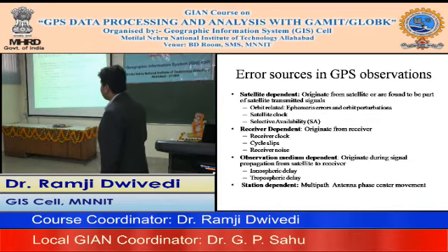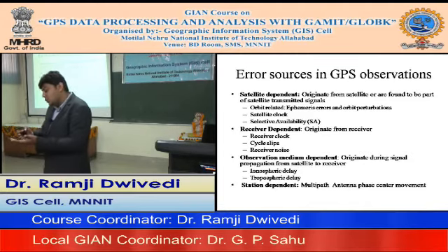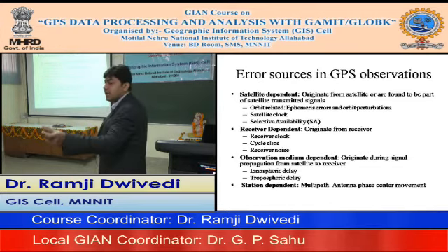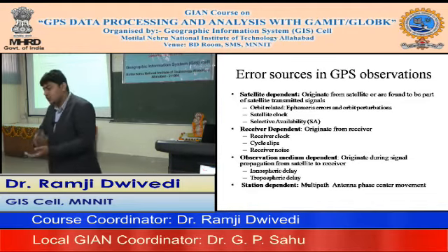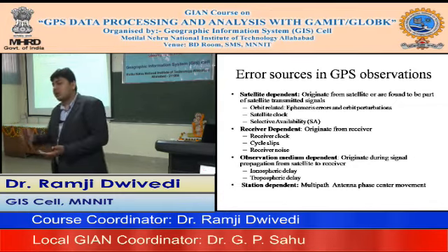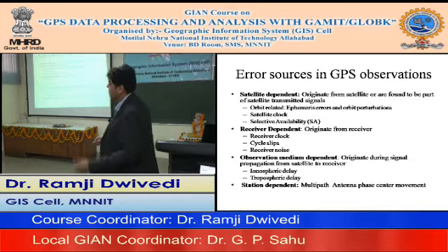So for the satellite clock drift, the parameters you could use are coming through the navigation message, which we discussed yesterday: A0, A1, and A2. So you could compute the DT term with respect to the satellite, and estimate the corrections which are applied to the satellite. It is also a general understanding that the satellite clock bias is properly known well before you take into account the XYZ and the receiver clock offset. One of the reasons we consider the satellite clock error as well known is that the parameters we are using to account for it are properly given.